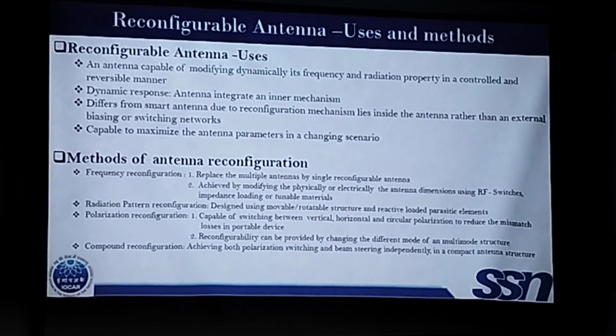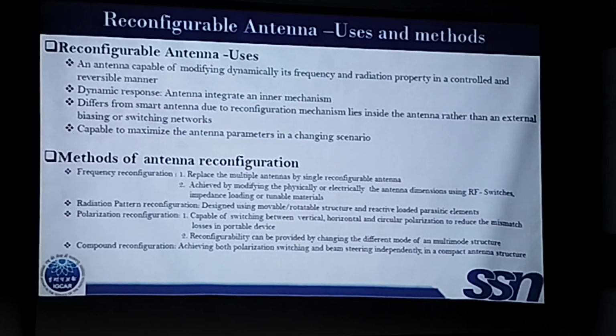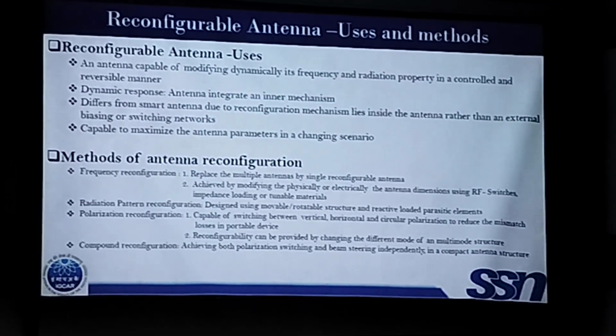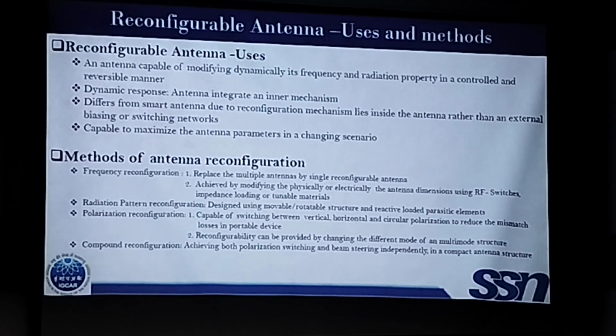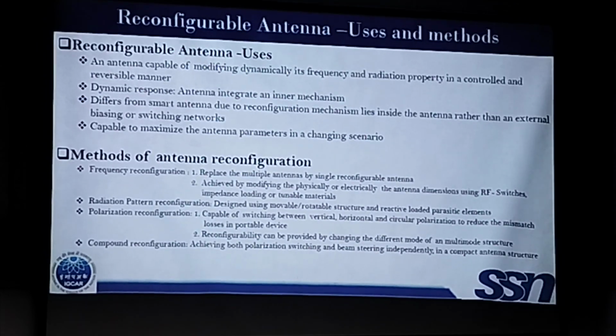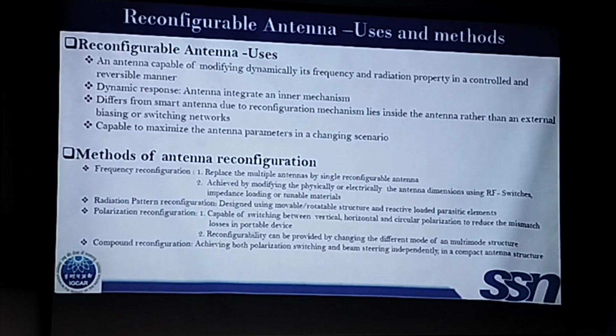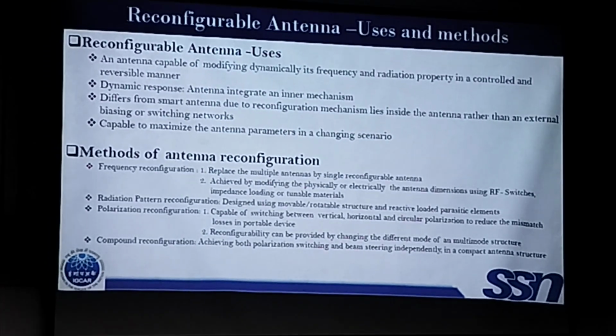That's how this dynamic performance antenna works. As for the method of reconfiguration, generally the major reconfigurable method is PIN diodes or diodes, switching on and off with electronic reconfigurability. By varying the effective length of the antenna, we call it the electrical length of the antenna.